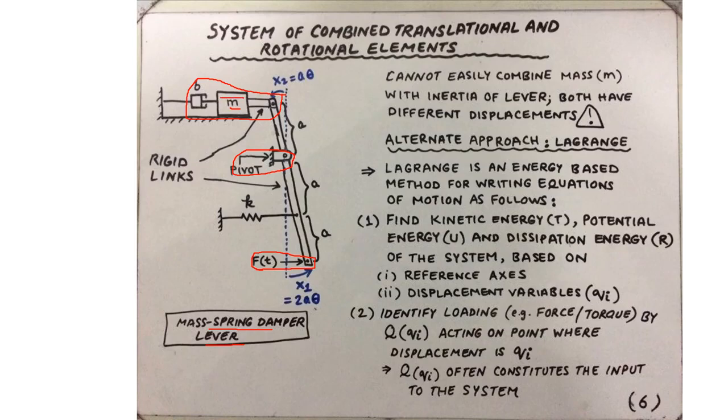So if the force displaces the lever at its bottom end to the right hand side, then the lever will exhibit a rotational motion specified by the angle theta, and as a result, on its upper terminal, it is going to move left and push the mass leftward, and therefore the motion of the mass is a translational motion.